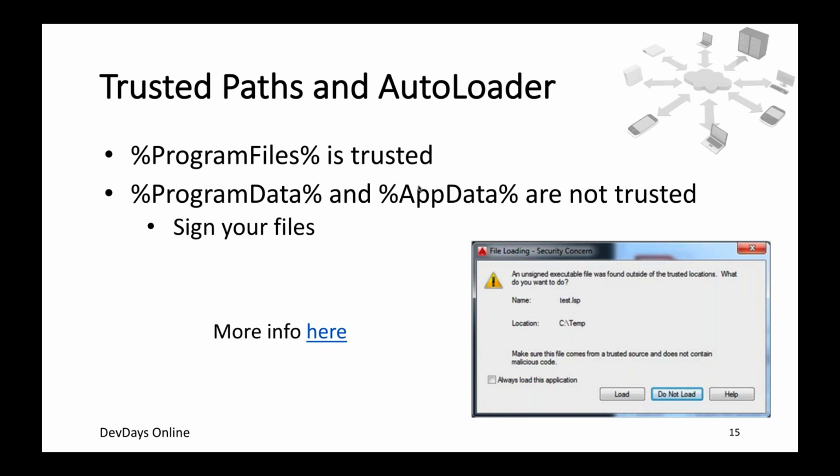And trusted means one of two things. It means either the DLL has been installed into the program files folder. The justification for that being that if anybody has managed to install something into program files, it means that you gave a top level of trust to the installer that did that, which means that you have said that, hey, I trust this thing, AutoCAD, you don't need to worry about it.